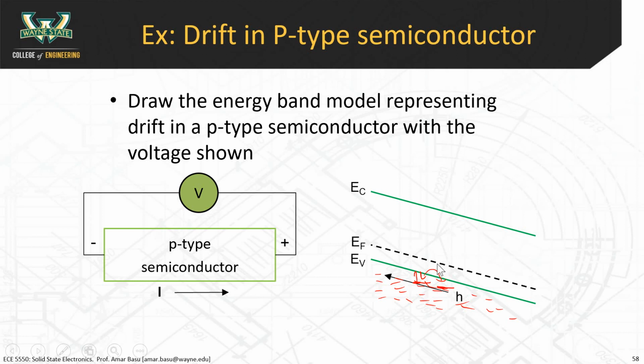So again, the electron sees a lower energy state that happens to be empty. The electron moves in this direction, and the hole transfers in the opposite direction. So holes are moving to higher potentials, or what seems like higher energies in the energy band diagram, because the electrons are actually moving to lower energies.